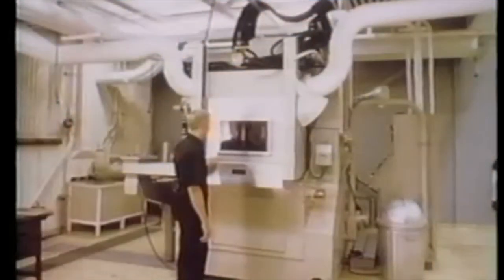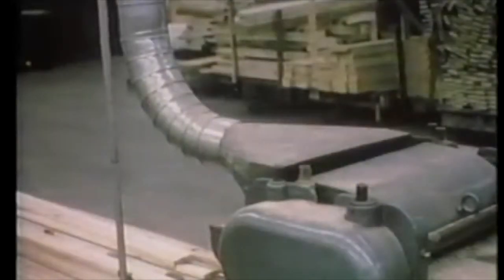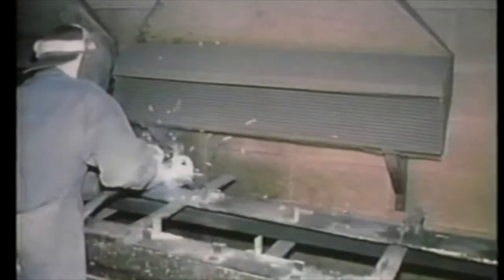Remember to enclose the source as much as possible, or bring the hood as close as possible to the source. The hood must be compatible with the worker and work practices. If it interferes with the work, productivity will be lost, or the worker may alter the hood, making it less effective as an emission control. This receiving hood over an induction furnace was cut by employees because they could not see inside to check the melt.